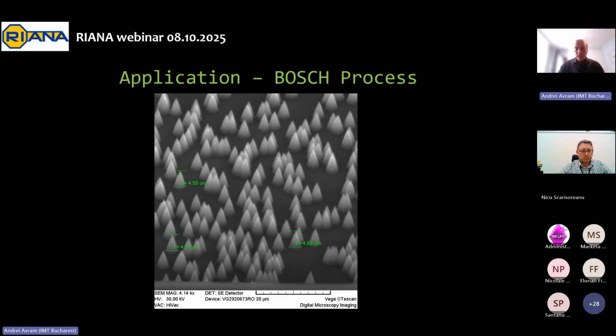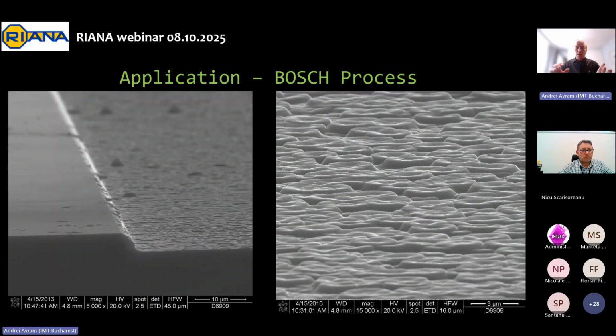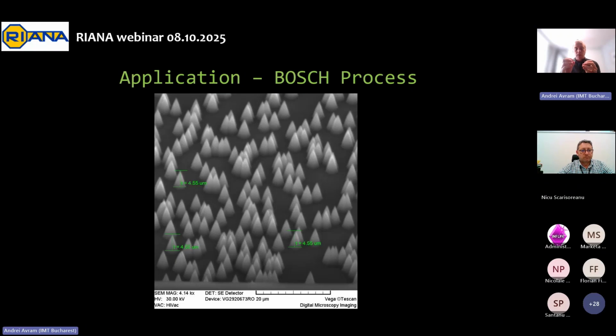You basically get some etching, and at some point, because the passivation is not evenly removed from the horizontal surfaces, you start to get some roughness on the surface, which increases, and those points of roughness actually get more easily coated with passivation layers, and you are not able to remove them anymore during your process. So this is something like that.